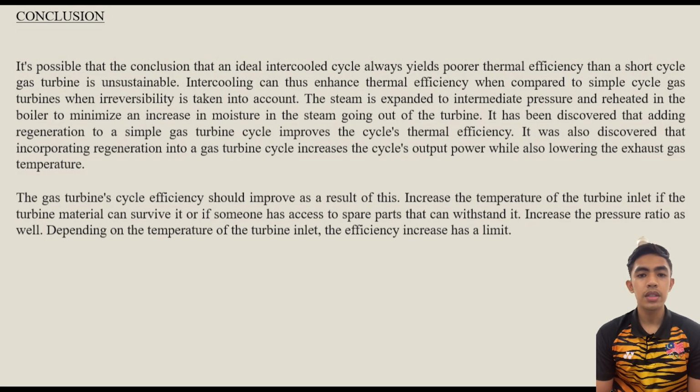It has been discovered that adding regeneration to a simple gas turbine cycle improves the cycle thermal efficiency. It was also discovered that incorporating regeneration into a gas turbine cycle increases the cycle output power while also lowering the exhaust gas temperature.